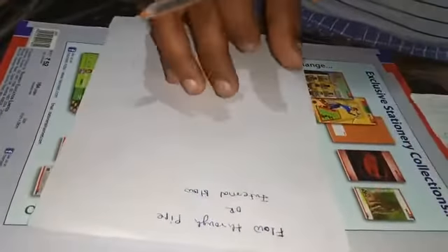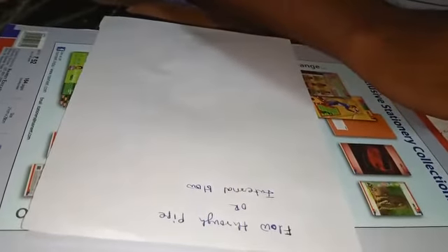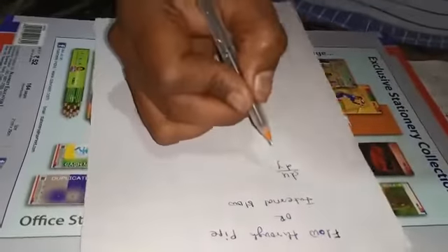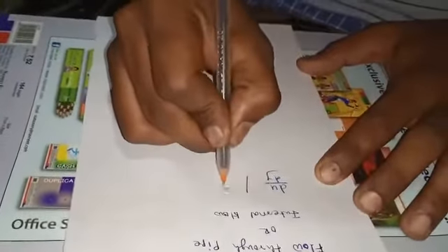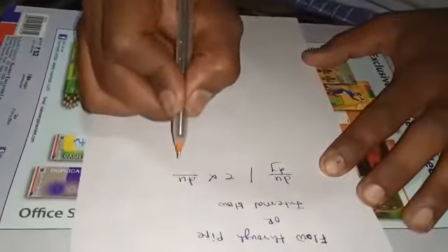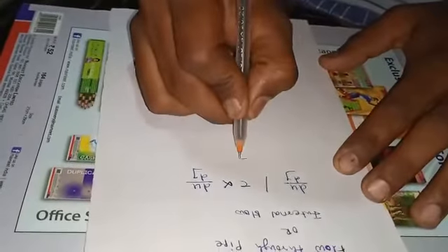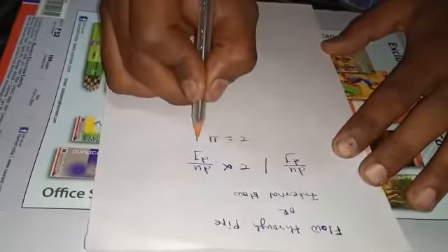Now in this unit we will see the flow of fluids which are viscous and flowing at very low velocity. As you know, at low velocity fluid moves in layers, and each layer of fluid slides over an adjacent layer, and due to this relative velocity between layers, the velocity gradient du by dy exists. Hence we know from the first chapter, from Newton's law of viscosity, that the shear stress is directly proportional to this velocity gradient du by dy. To remove this proportionality, we need one constant, and such a constant is called the coefficient of viscosity, mu.